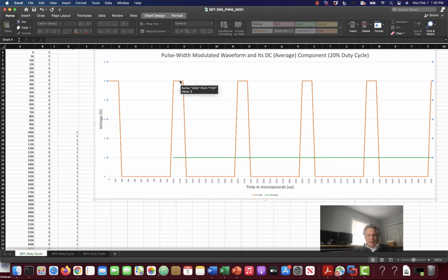0.32. So for 1/5 of the time, that transistor would dissipate 0.32 watts, and so its effective power over the whole cycle would be 1/5 of that, would be about 0.064 watts.